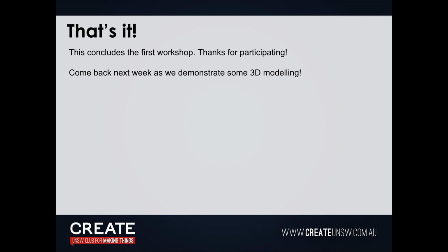You need to show how to combine stuff. I can't remember how to do that. It's in create or modify. Modify. Yeah, you can combine. So if you want all these bodies to become one body, you can combine it. Yeah. Target body, that's fine.